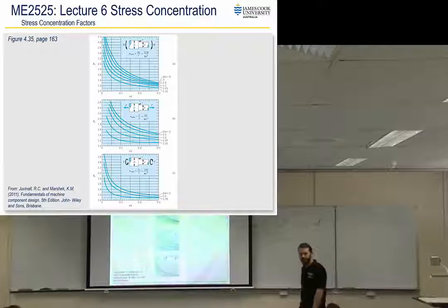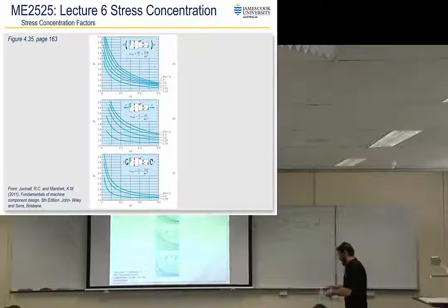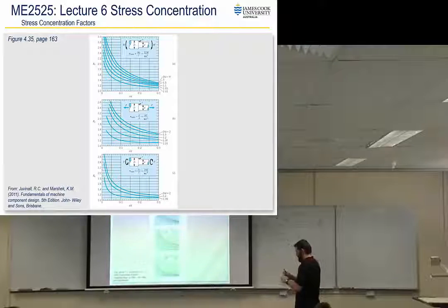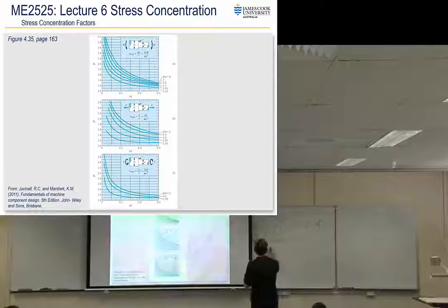Alright, how are we going? Everyone had a crack? Alright, so the way I lay these things out is we just write down some ratios and the values. No need to stuff around. So what value of big D on little d do we get? 2. Little r on little d is 0.25, so therefore KT, what do we get?